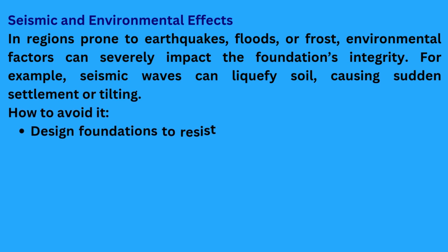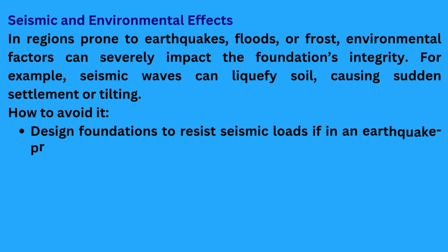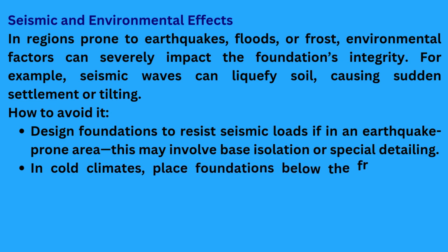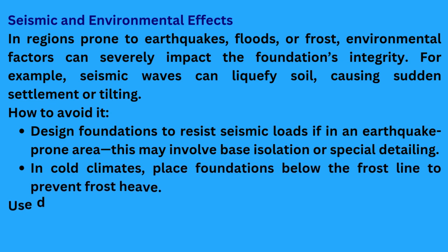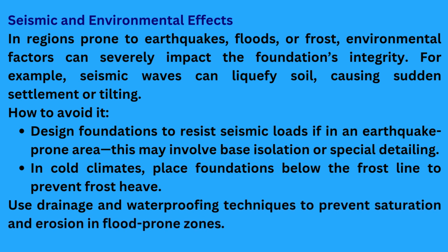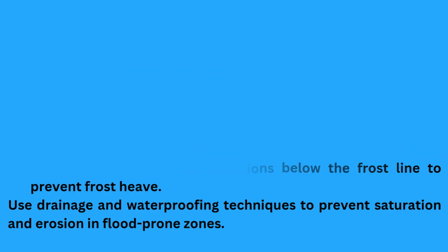How to avoid it. Design foundations to resist seismic loads if in an earthquake-prone area. This may involve base isolation or special detailing. In cold climates, place foundations below the frost line to prevent frost heave. Use drainage and waterproofing techniques to prevent saturation and erosion in flood-prone zones.